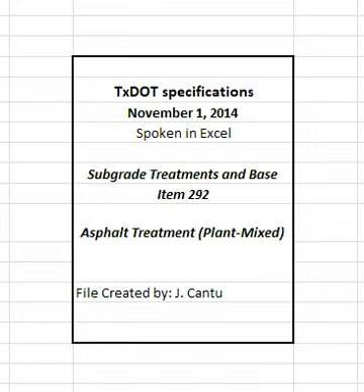The engineer will evaluate the mixture for moisture susceptibility in accordance with TEX 530C unless otherwise shown on the plans. A maximum of 10% stripping is allowed unless otherwise shown on the plans. The test sample will be retained and used to establish a baseline for comparison to production results. The engineer may waive this test if a similar design using the same materials has proven satisfactory.